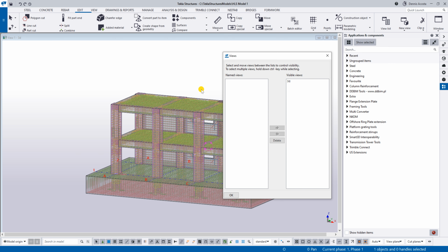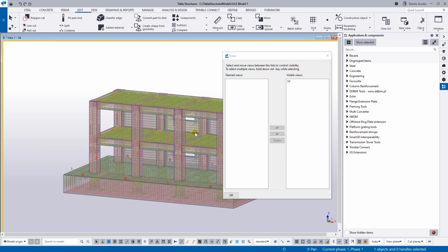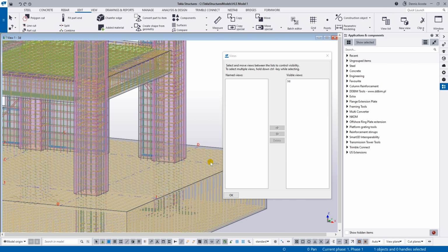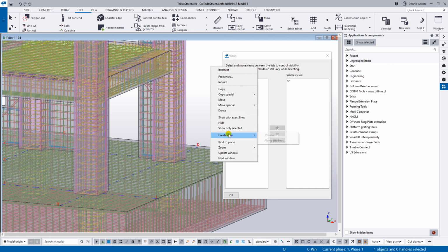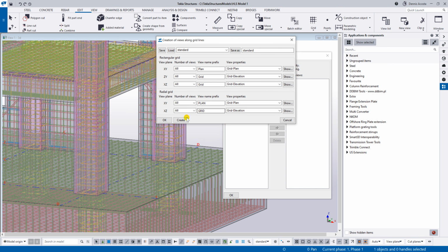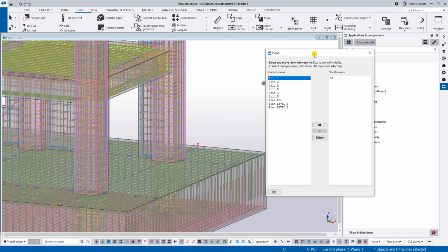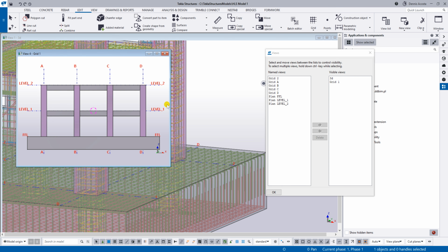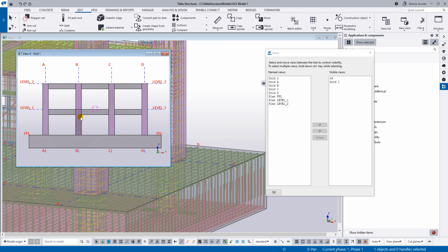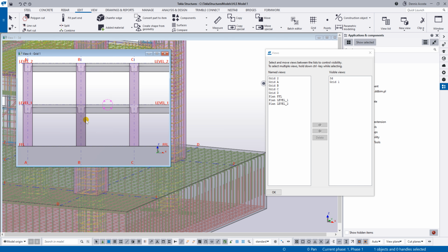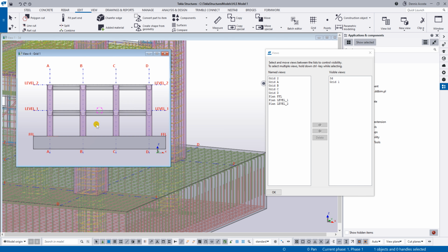I'll delete this one. Fit work area. All right. So here, select the grid line, right click and then create along grid line and then hit create. So once you create that one, it will be placed in our grid list. Okay, so see, and then if you control 2, if you notice there's no rebar here, right? Because it's hidden. Okay, no worry about that one.